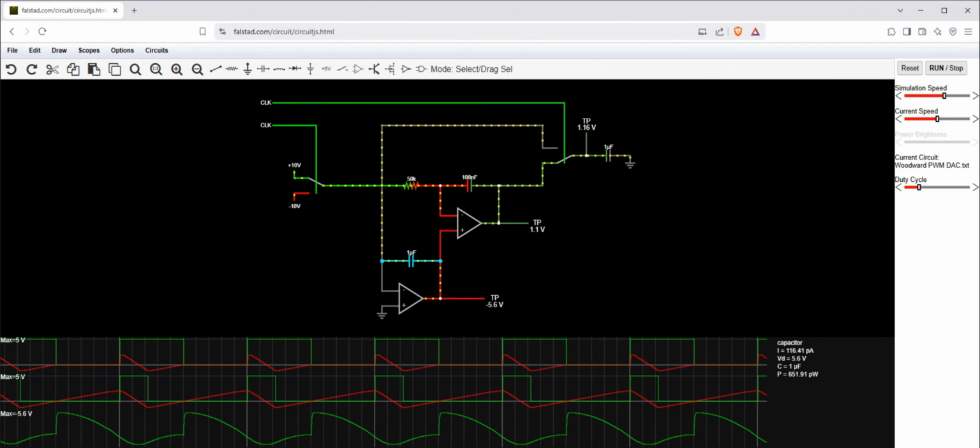The counter wrap value can also be selected with a similar flexibility up to 16 bits. The resulting DAC has some pretty but hard to understand waveforms. The integrator is mostly centered around 0, rising towards the peak value at mid-scale and then falling back. The sample and hold circuit samples during the first half of the PWM period and goes into hold exactly as the integrator crosses 0, preventing transient currents in the hold capacitor with a steady output.